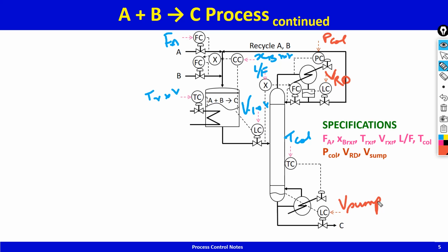That's the point that I've been always trying to make, that you've got degrees of freedom, and in order for the process to end up at steady state, you need to understand material and energy balances and make sure that all independent material and energy balances are closed. And in order to close those, you need to specify appropriate variables.